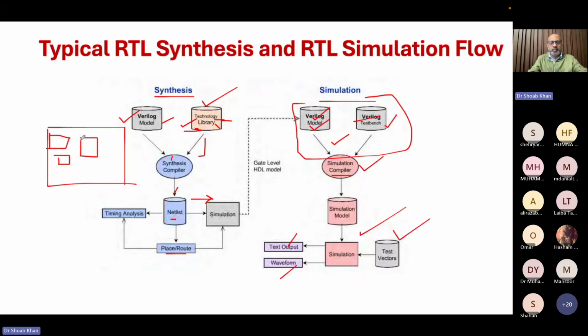Kind of the same thing happens here as well: the people who are doing place and route give the timing constraints. Primarily, they want to meet the timing, that a signal and the data that goes from one set of registers to another set of registers must not take more than this much time. So obviously they have to place where the data is moving closer together. But obviously they cannot put everything close together, so you've got to compromise. So this becomes an NP hard problem.